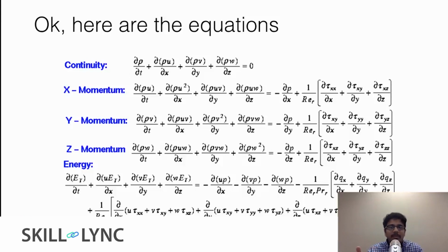One thing you need to remember is that irrespective of the problem that you're solving, you are always solving these equations at the end of the day, because these equations describe how the flow takes place without taking into account the application. The way these equations are able to understand that the flow is taking place over an airfoil or over a truck is from the boundary conditions. We will be talking about these more when we actually derive these equations.